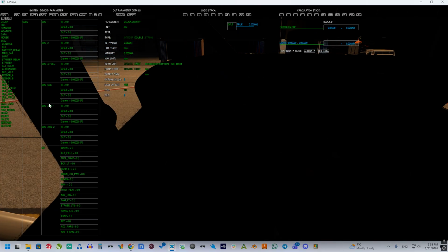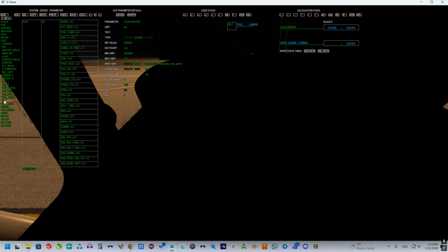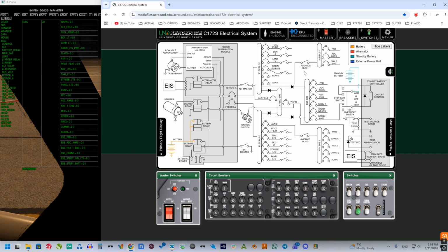But now I just done it for avionics 1 and avionics 2 buses. And last thing, I add all the circuit breakers that are present in the electrical circuit, all of these circuit breakers. So the next is to calculate all consumers and their current for all other buses, and calculate final current in this part of the schema.